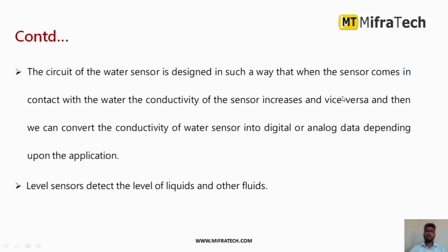Depending on the increasing conductivity, we can measure the water level and send it to any microcontroller interfaced with it. This level sensor detects the level of liquids, not only water; you can measure the level of other fluids also.